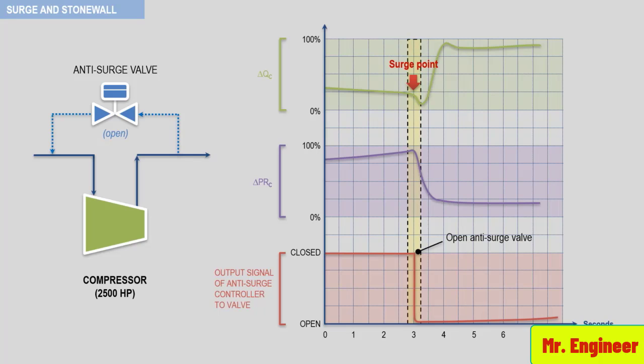This fact is important to remember when trying to justify a field surge test to plant operations. A compressor will never be damaged by a surge test if conducted properly. As shown in this figure, process chart recorders are used and the surge system is in automatic. But the surge control line has been moved to the left of the actual surge location.